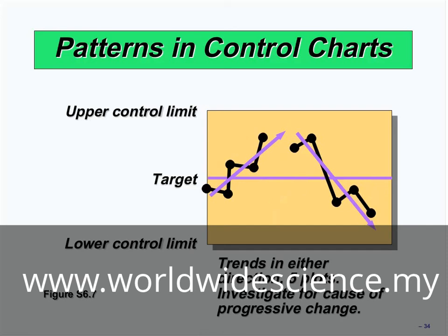Here, all of the spots have fallen inside the area, but the process is not under control. Despite all of the spots having fallen inside, we should tell the process is not under control because we have a trend here, upward trend or, sorry, downward trend.